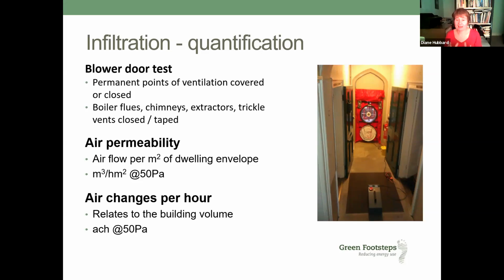So it's just an air change rate at 50 pascals. Now that's more commonly referred to when you're thinking about passive house standards. And an air change rate is used there. It's calculated in a slightly different way to how we'd calculate it in the UK, but we can leave that for another time really. So air permeability is really the key thing.